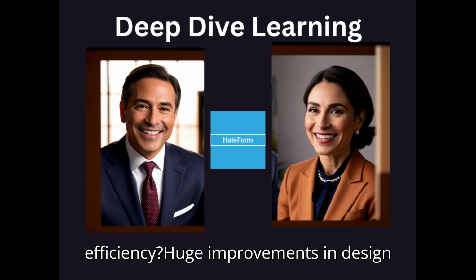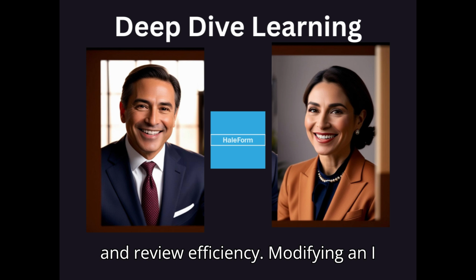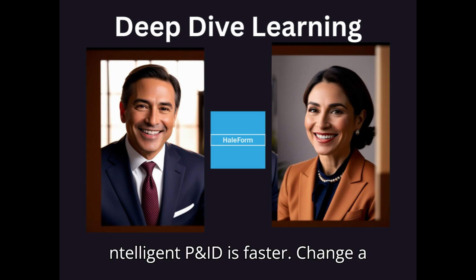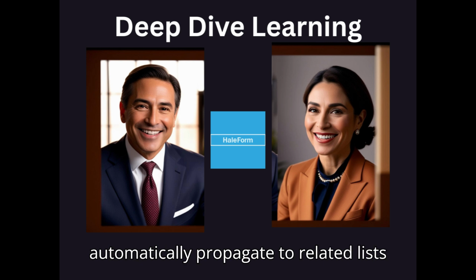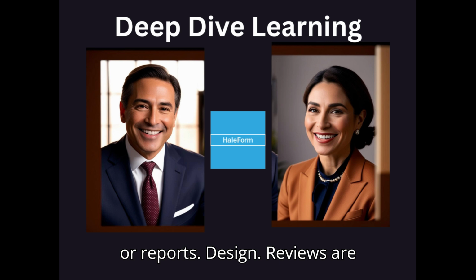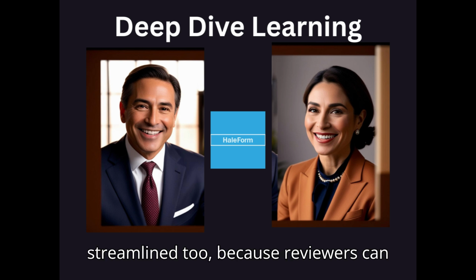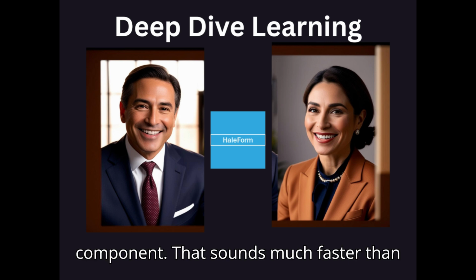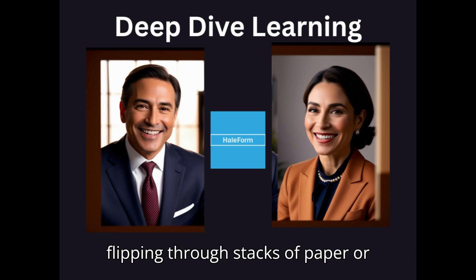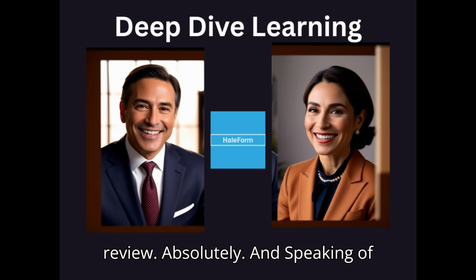What about efficiency? Huge improvements in design and review efficiency. Modifying an intelligent P&ID is faster. Change a valve specification, and that change can automatically propagate to related lists or reports. Design reviews are streamlined too because reviewers can access data directly from the diagram, just by clicking on a component. That sounds much faster than flipping through stacks of paper or multiple electronic files during a review.